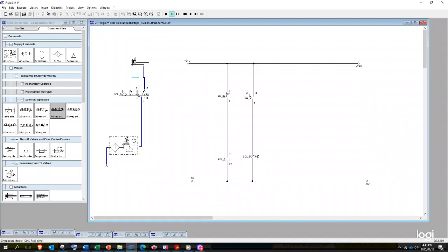So how are we able now to have this bouncing or spring effect, where the piston rod or the wooden boards advance and retract at the same time? It is because of this spring effect that we have on our valve, our solenoid operated valve.